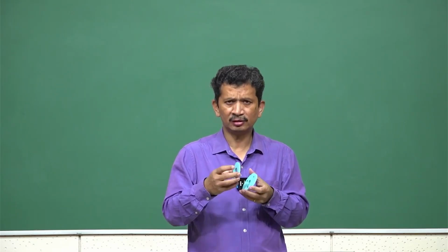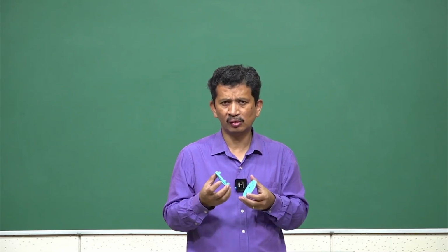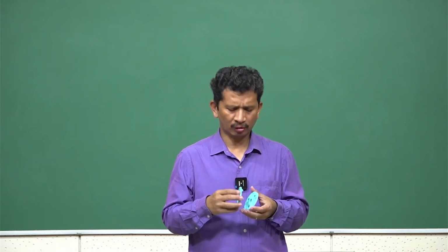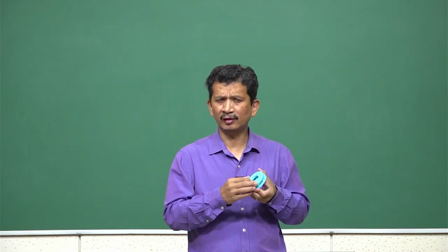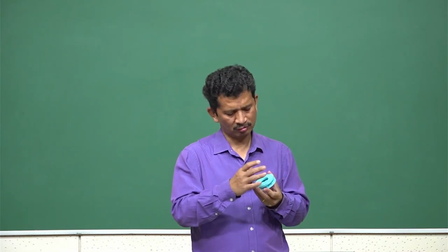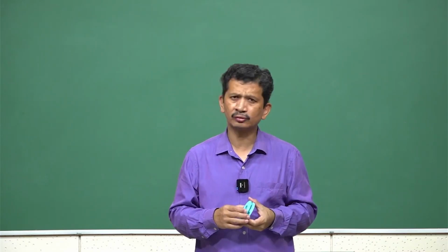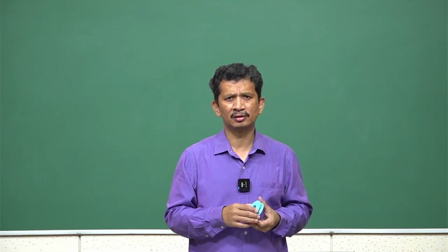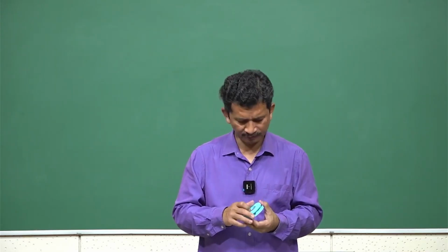So, any change in the length between the 3 balls, or even the contact points here, will be accommodated automatically. Yes, in this case it is not symmetric, so it will go off. We will also talk about the concept of thermal center, which is used in precision machine design.